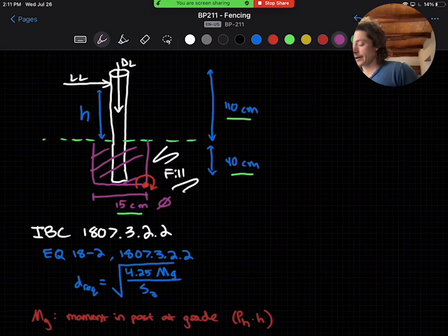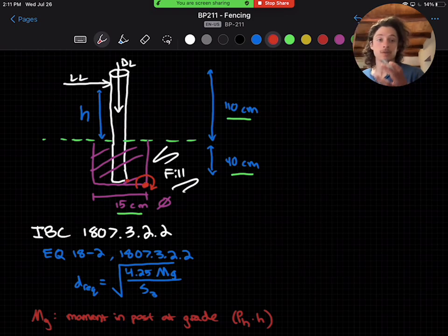And I've drawn this diagram out here to also give you a little more perspective if we wanted to draw a free body diagram of what is happening here as well, to have another mode of calculating that D required. We have our fill and we have our point of rotation of the block, and if we're checking each component, we'll want to be checking first that the post isn't rotating in the block about this point, and then again that the block and post, once we can determine that it's one singular object, isn't rotating within the fill.